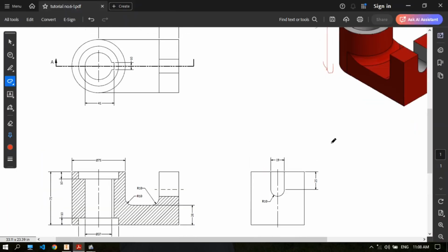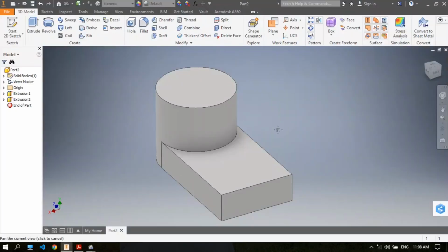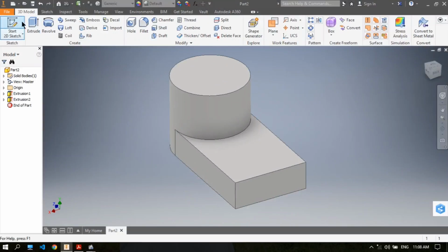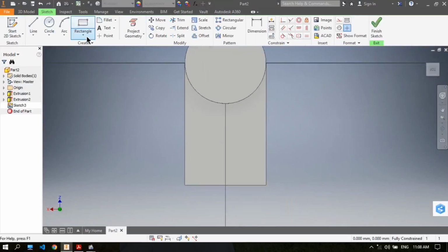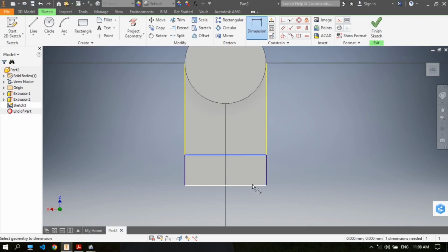Okay, and then we make this rectangle on it. So choose sketch and then the plane on it. The sketch is automatically up to normal, and choose rectangle here on the corner here, and then right click. Okay, and then put the dimension on it, that line and that line, 28, enter. Okay, this is the blue sketch. Blue sketch is the fixed position.